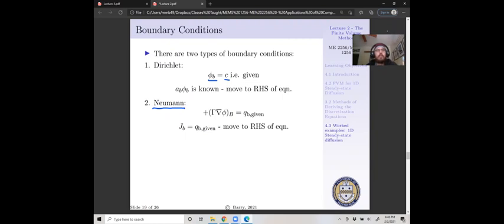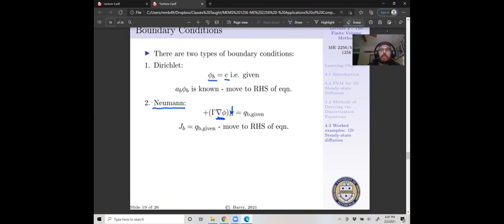You'd have two boundary conditions in one location for a second order differential equation that needs at least one boundary condition on each end. So for a flux, we're going to indicate that we'd have a positive diffusivity times the gradient of our conserved quantity phi, evaluated at the boundary. I guess I should make that a lowercase, huh? Just for consistency.